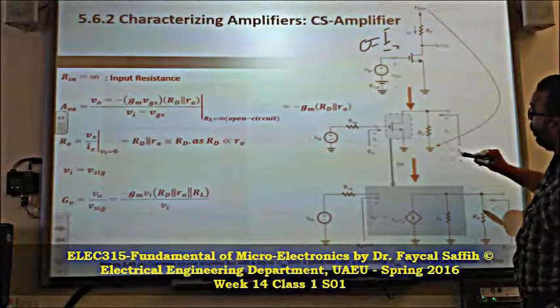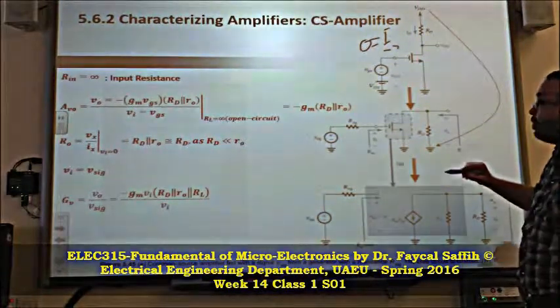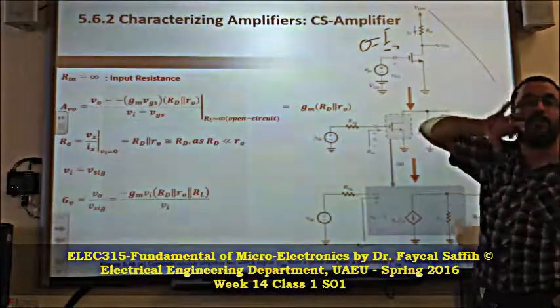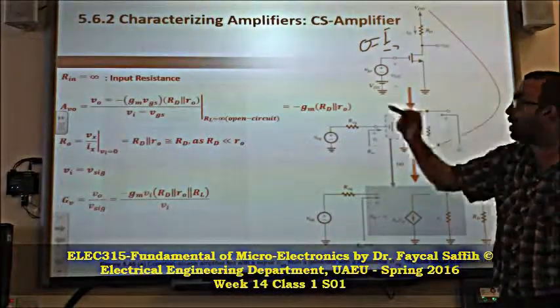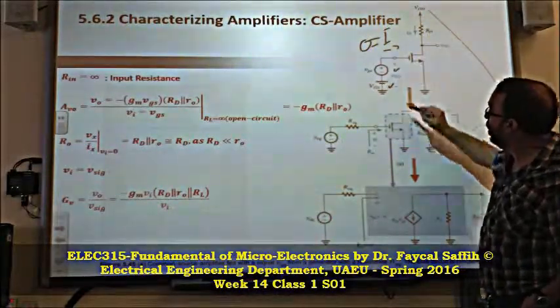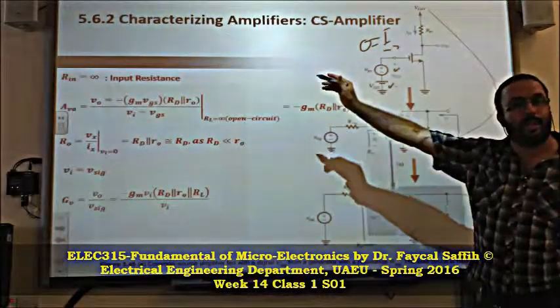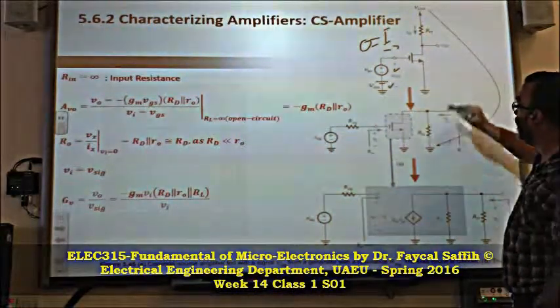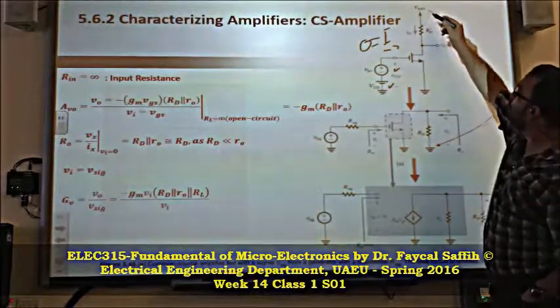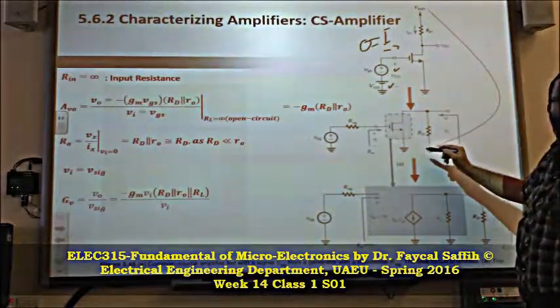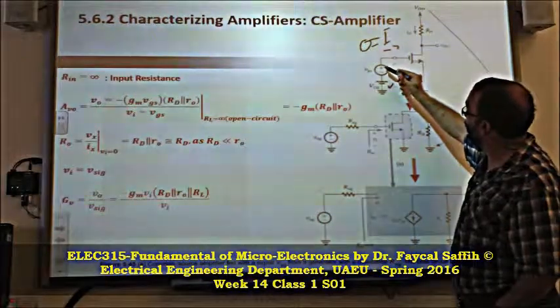Here is the first amplifier in DC and AC, so we have to go to the AC domain. In DC, we already found the quiescent point. So we bring VDD to the ground, yes or no? Yes. And we have to take this out.